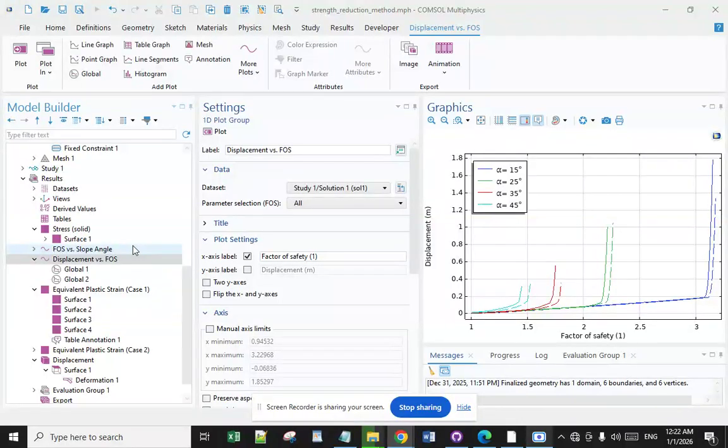First, the role of each mechanical parameter in slope destabilization was investigated theoretically and numerically using COMSOL software simulation, and the results indicate that the effects of elasticity, Poisson ratio, and soil gravity on the evaluation of the factor of safety, or FOS, are insignificant and can be neglected compared with the cohesive force and angle of internal friction. Next, an improved method was constructed to correlate the FOS with cohesive force and the angle of internal friction.